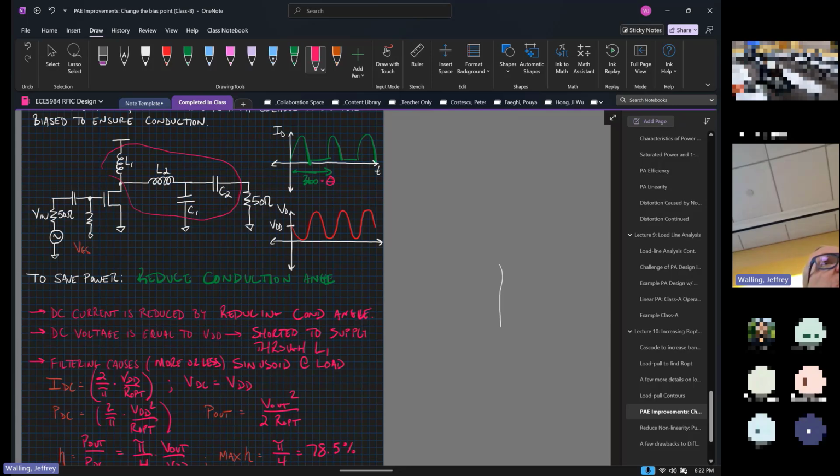Because you're saying that comes from the Q term? Well, I would be careful there. The Class A, just by definition, is an amplifier where I'm conducting for 360 degrees. In the Class B, I'm defining it as something that's only conducting for 180 degrees. So the drain current waveform in and of itself is nonlinear before I've done anything that causes it to compress. If I start driving the device harder, this waveform is not going to look like this beautiful half rectified sine wave. It's going to start to distort, and as it starts to distort, there's more harmonic content there. Now that's a hand wavy way of looking at it, but the less that waveform looks like a half rectified sine wave, the more other stuff I have in the waveform if I were to do a Fourier series expansion.